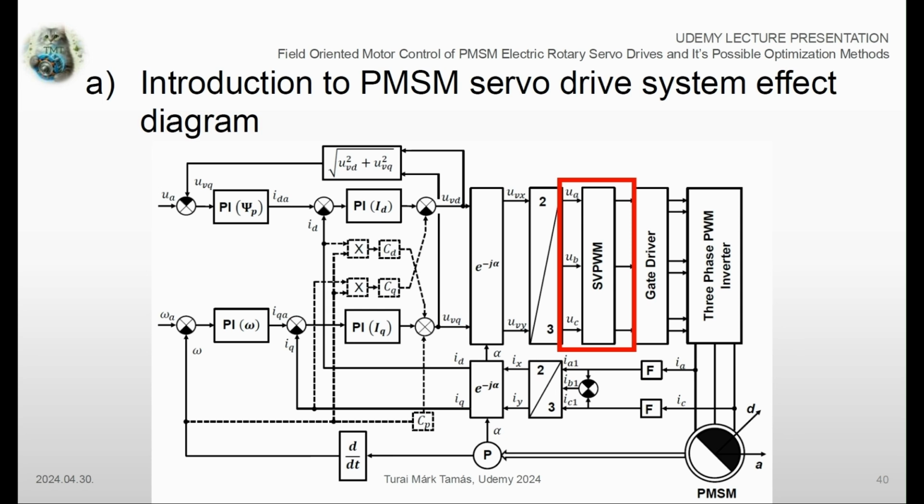This method is the end of the field-oriented control algorithm that we are going to cover within this course. A so-called platform software is needed to transfer the requested phase voltage values to actual IGBT switching signals in the three-phase inverter. The gate driver hardware component is responsible for driving these IGBT semiconductors according to the low-power control signals coming from the microcontroller itself.